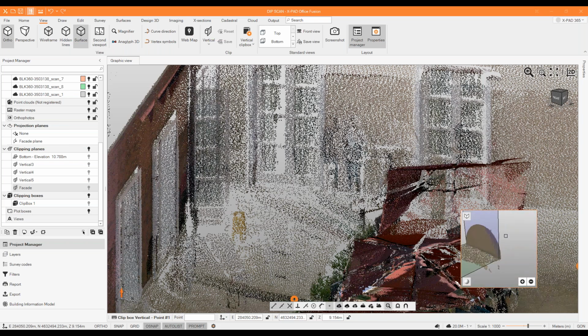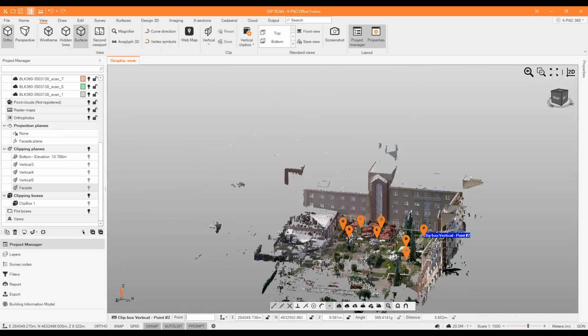So if you want to select another functionality from the Smart Magnifier, on the top left side, we have also the automatic plane recognition. What does it mean? It means that you can easily select points on the point clouds, and with this specific functionality, maybe a part of the point clouds close to this planes intersection is hidden. I can select a point on one of the two facades and automatically it will project it in the plane intersection.